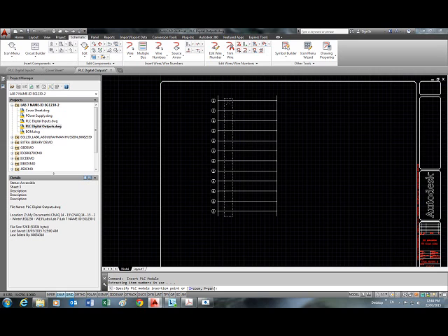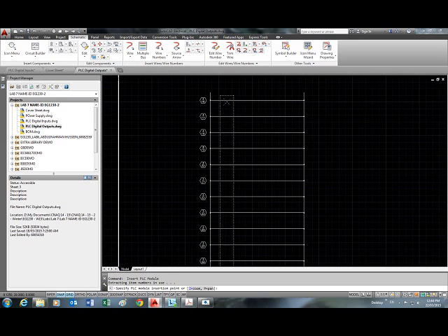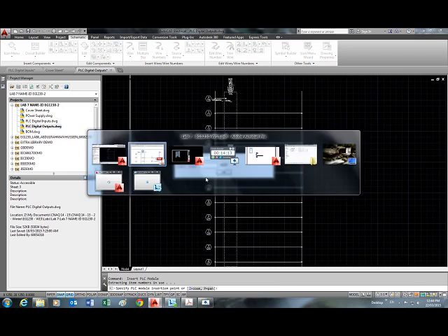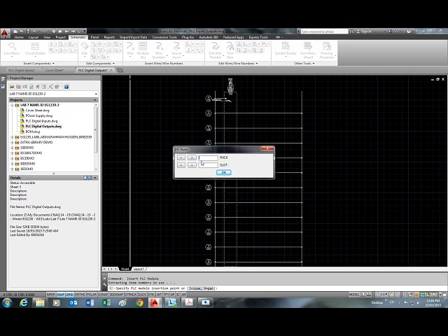There's the module. This time we want to align to the left because this is an output module. And align the X with the wire and then click OK. Same as we did before. This is now still rack 1, but slot number 3.